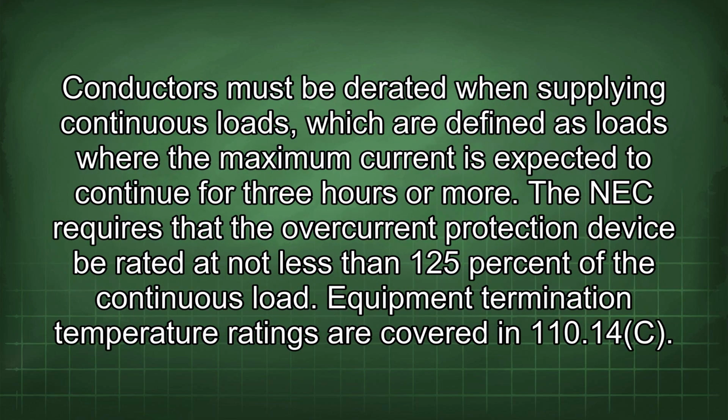Conductors must be derated when supplying continuous loads, which are defined as loads where the maximum current is expected to continue for 3 hours or more. The NEC requires that the overcurrent protection device be rated at not less than 125% of the continuous load.